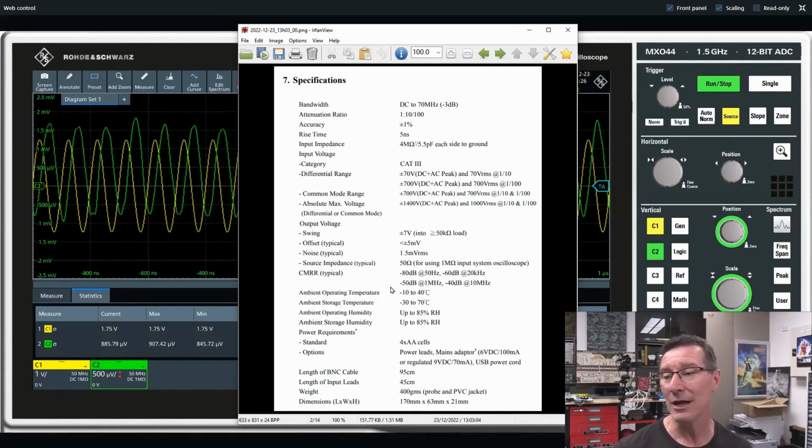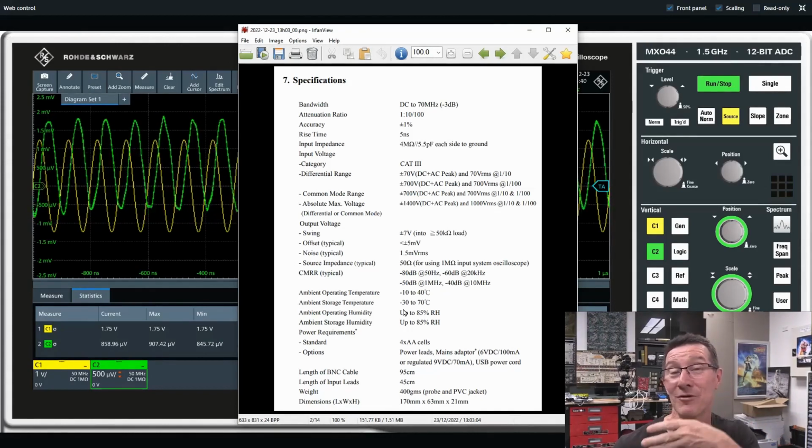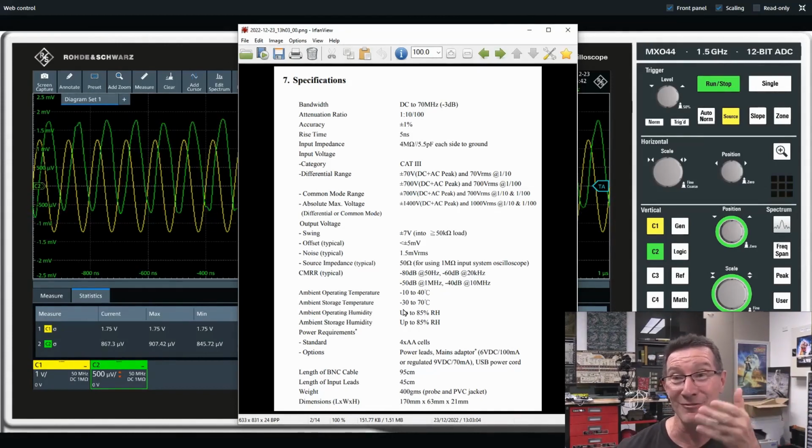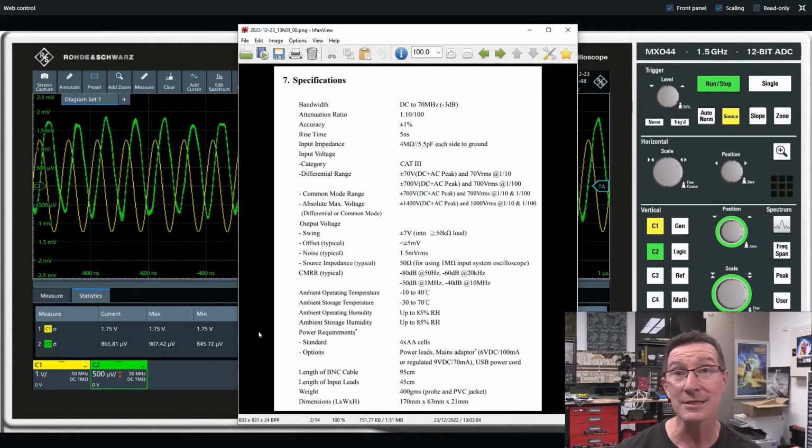Now, a good data sheet should actually specify that and tell you exactly what it is. This is a good marketing trick, because marketing can make the common mode rejection figure sound a lot better just by saying that's input referred instead of output referred. So just don't get caught by that.